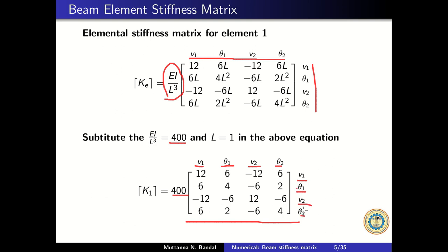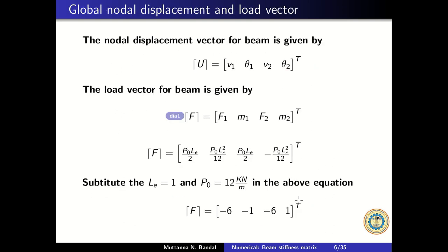Okay, so with this, let us substitute that stiffness matrix into the equilibrium equation. Already we have discussed the nodal displacement vector and the force vector. The load vector is given as F equal to F1, M1, F2, M2: shear force, moment, shear force, moment at each of those nodes.